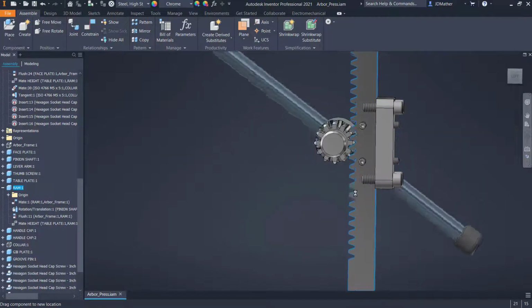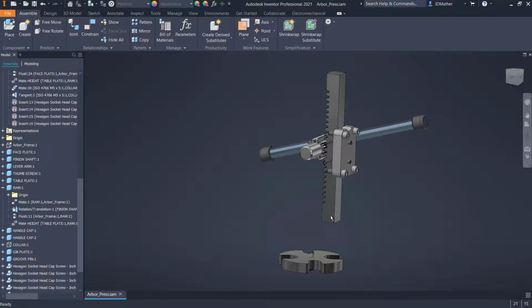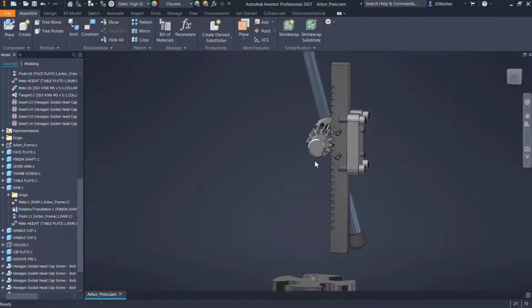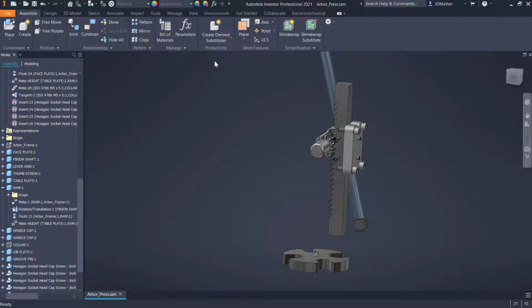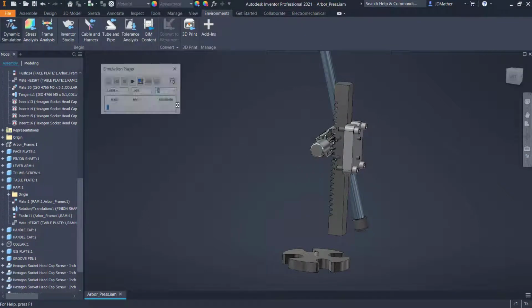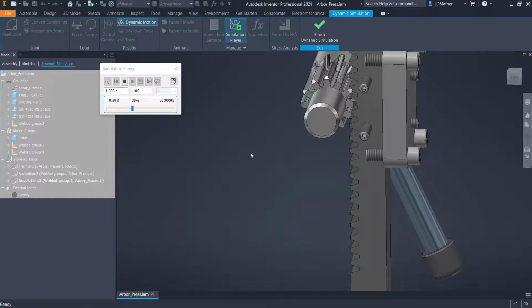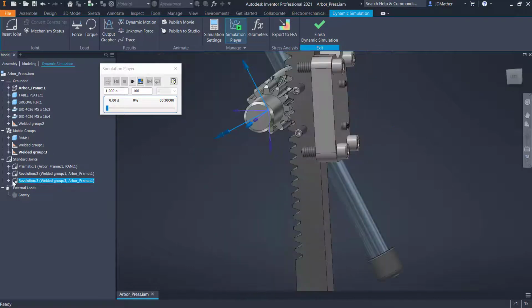All right, so if I drag this, we see the motion. Now that kinematic motion doesn't give us any indication of forces, so we have to get a rolling cylinder on plane joint in order to calculate forces in dynamic simulation. If I go to the dynamic simulation environment, I have a prismatic joint. This can only move in 1 degree of freedom, straight line translation, and then a revolution joint for this part, and I'm not sure why there are 2 revolution joints there. We can drill down actually and find out.